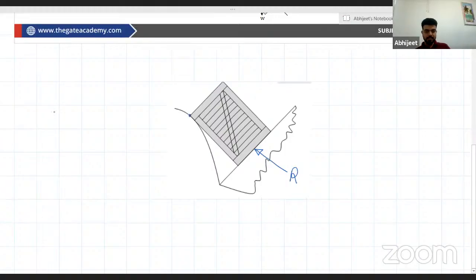Now at this point there is a sharp edge and there is a curve. So what happens at this point? We cannot draw the tangent, and the normal will give you the reaction at that point. When two curves are in contact, the common normal will give you the direction of the reaction. But here the sharp edge and the curve are there. If we see, the whole system has only three forces acting on it: one the reaction from this, one this mass, and the other from here. Now the direction of this will not be like this or like this.